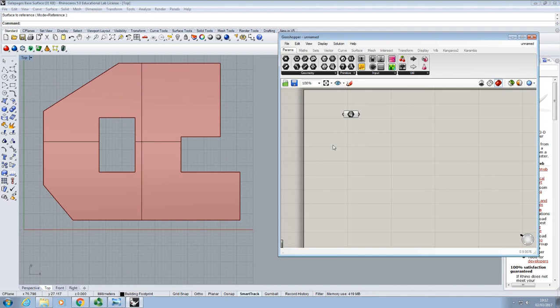The first one is going to be the grid origin x coordinate, and we'll use a slider to control that. So we're actually going to create 4 sliders here. So we could create that slider by clicking up here in input, dragging down a number slider, right-clicking on it, going to edit, setting that up. What we've shown you before is a shortcut where you can just type in a number followed by a few decimal places and get out a grid that way. There are also a few other ways of setting this up.